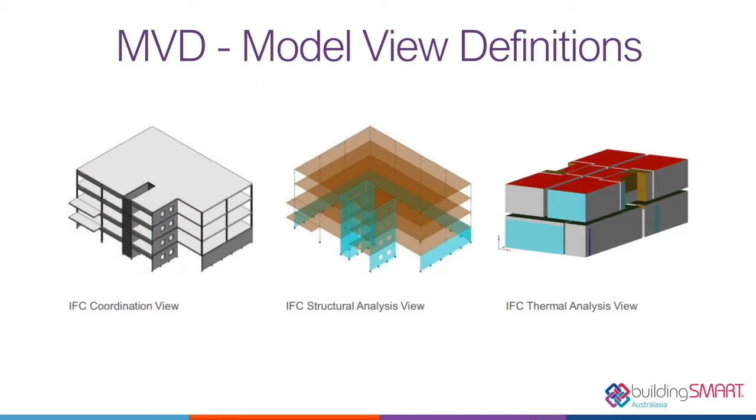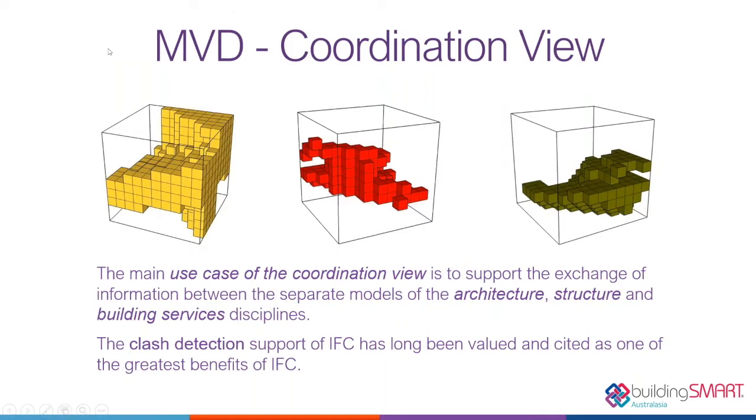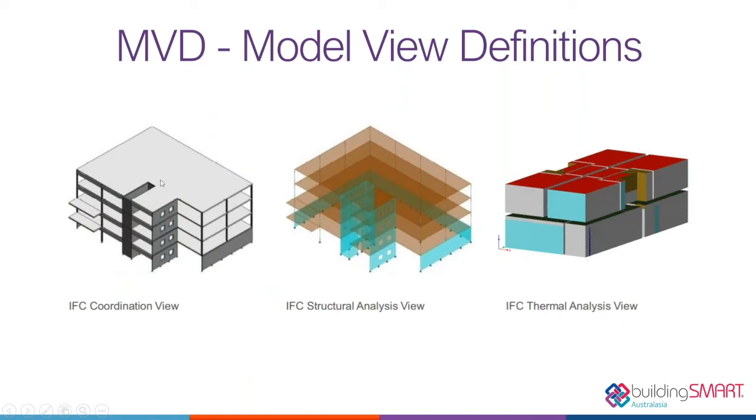I'm going to touch on a couple of other concepts which are important to understand when you need to either receive or generate an IFC file. Model view definitions are an important part of sharing IFC, and a model view definition is really a subset of IFC that relates to a particular use case. If you think an IFC data model is capable of, say, 1,000 concepts, then for any one use case there's a different requirement in the information you need to share, for example transferring a model for a coordination use case in contrast to a structural analysis use case or a thermal analysis use case.